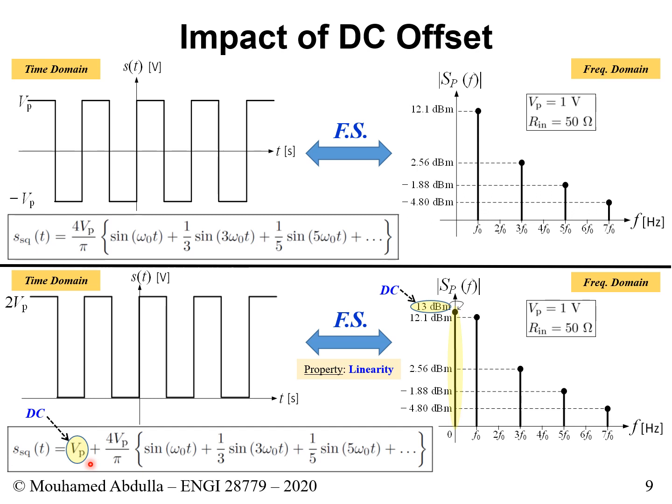Then you change this value to dBW. So basically you do 10 log 10 of the power that you got, the average power that you got. And then the result that you get, you add 30 to it. So if you do this on paper and you clean it up a bit, basically you'll have something like this. This is the result that you get. So anytime you deal with a DC value and you want to show it in dBm, this is essentially the equation that you have to use, not the other one.